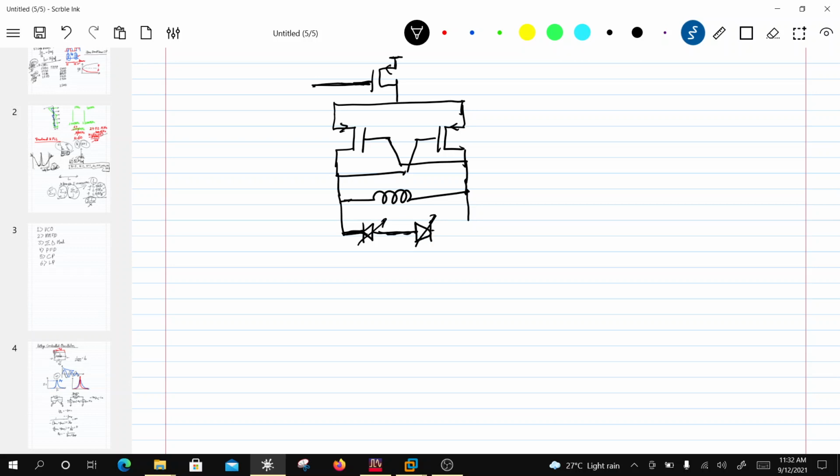Now let me explain a little bit about varactors. So there is a control voltage here. This is VC, and then you have got transistors, NMOS transistors like this, and they are cross coupled like this. So this would be called a VCO core, right?